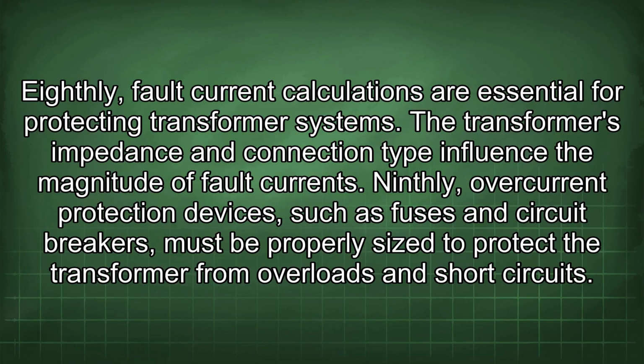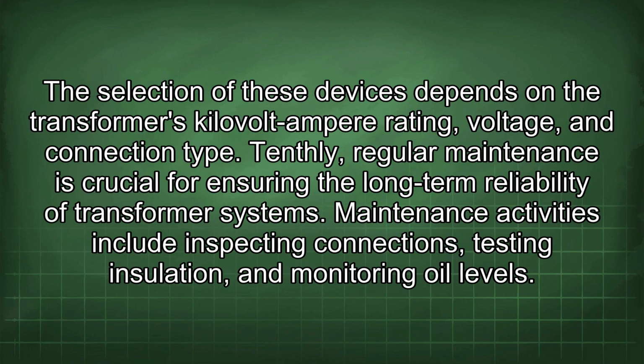Ninthly, overcurrent protection devices, such as fuses and circuit breakers, must be properly sized to protect the transformer from overloads and short circuits. The selection of these devices depends on the transformer's kilovolt-ampere rating, voltage, and connection type.